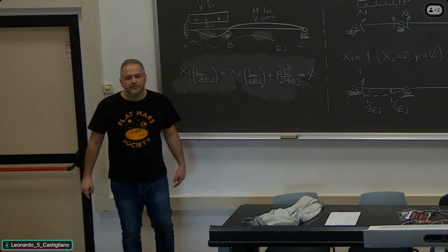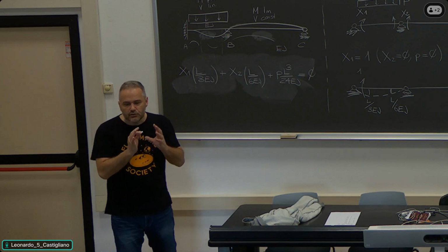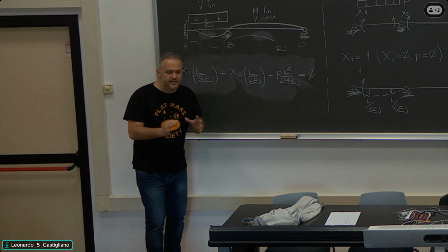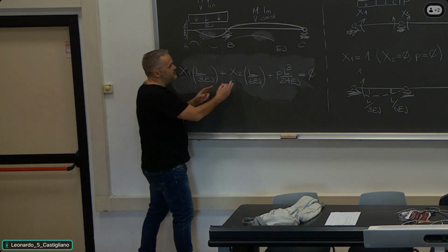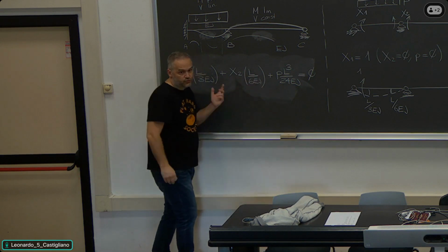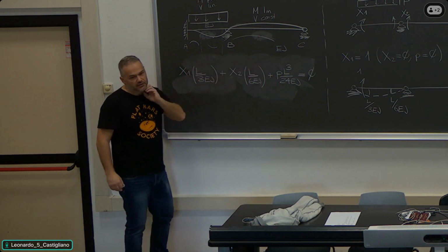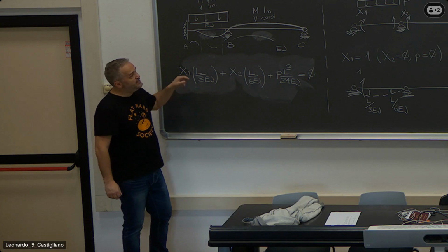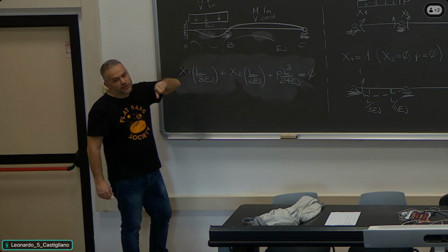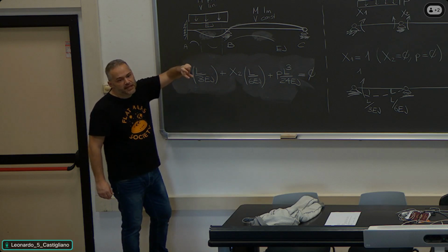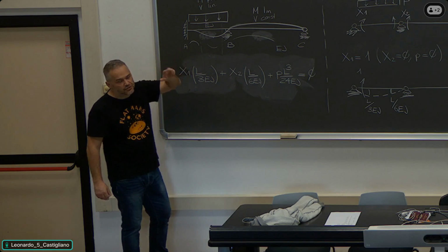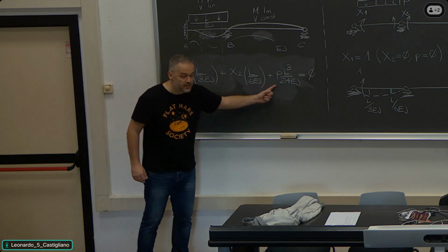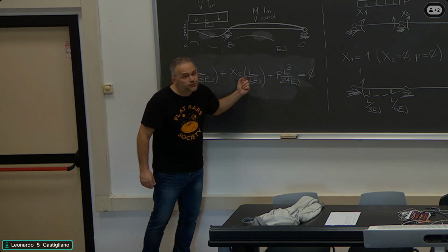Do not look at the formula as it is, look at the meaning of the formula. It says there are three effects acting on the structure, 2 bending moments and 1 external load. At the first point, when I remove the restraint, they create 3 clockwise rotations, 1, 2, and 3. The sum of these 3 rotations should be equal to 0.